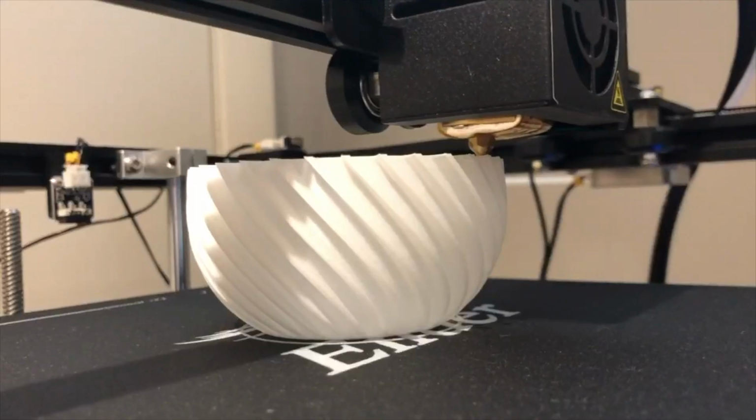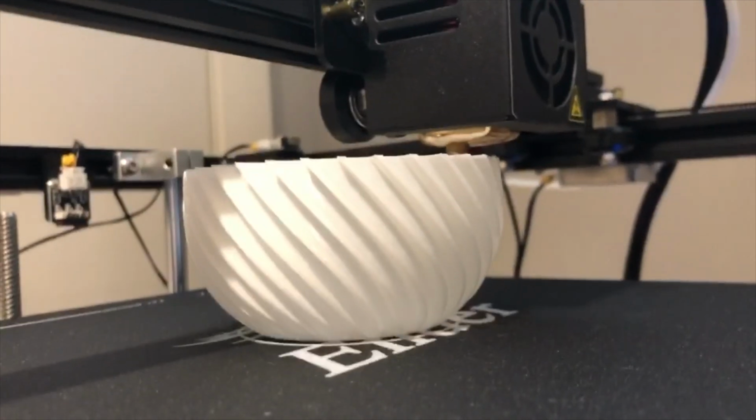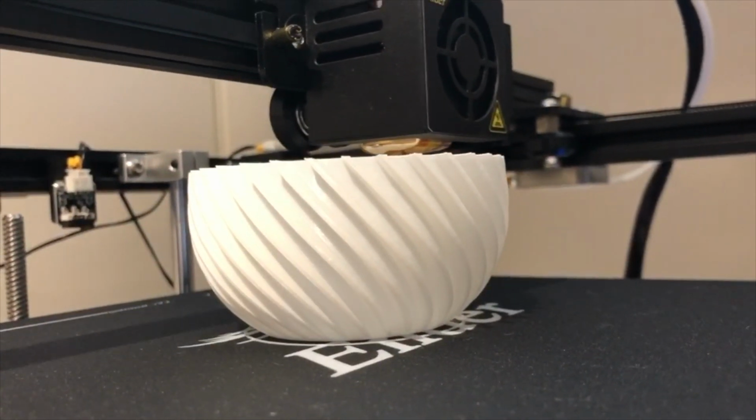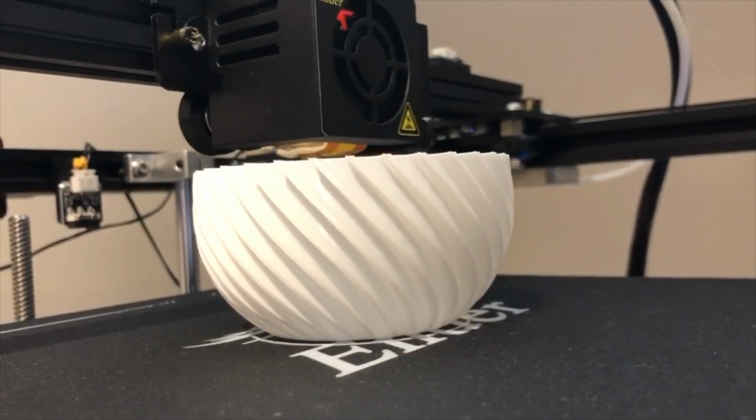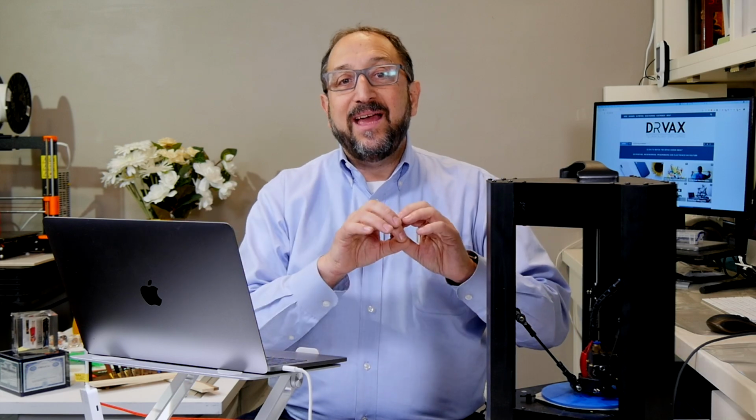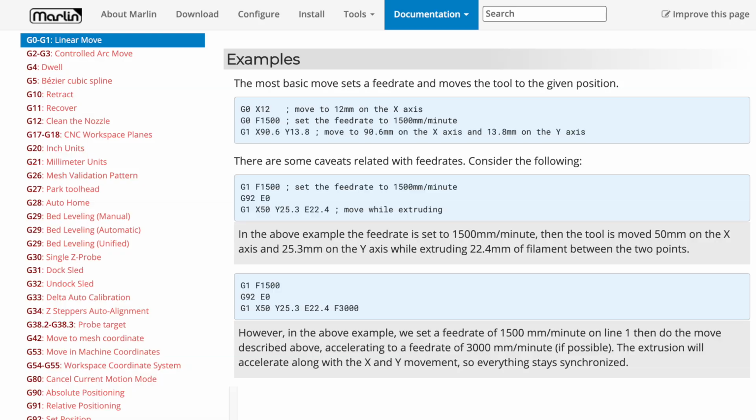A 3D printer is a form of a numeric controlled machine, and it uses GCode or geometric code, a variation very similar to the original GCode developed in the 1950s. One of the nice things about the GCode that's used by most FDM-style 3D printers is it's human readable. It's not in binary bits and bytes, it's in text. It's something you can read and learn to understand. And today, we're going to learn how to understand the variation of GCode that was created for RepRap 3D printers.